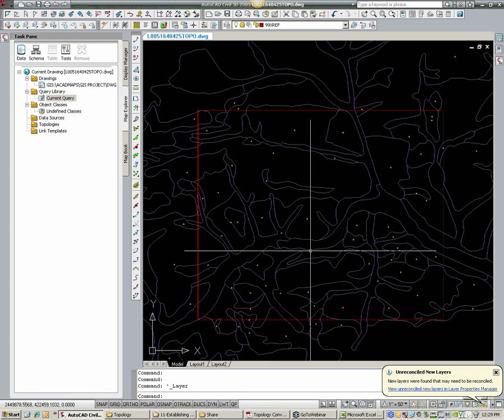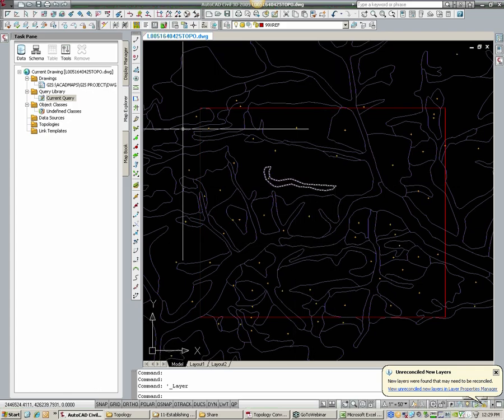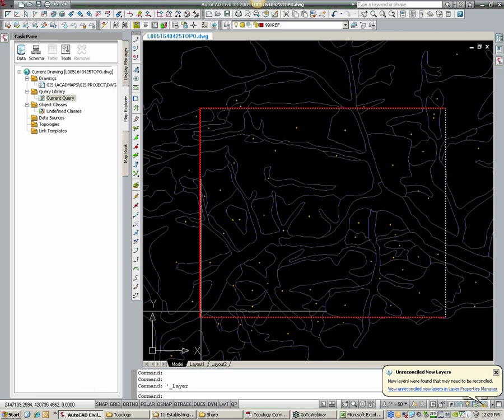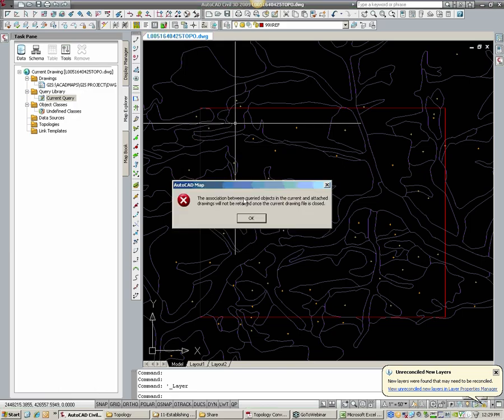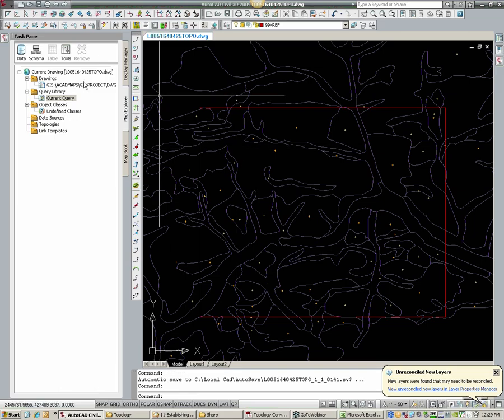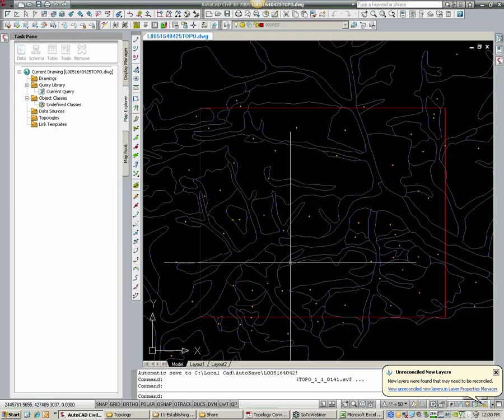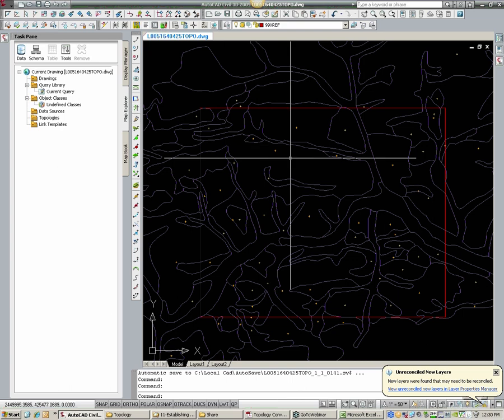Then the next thing I'm going to do is I need to bring these soils into my little area here. So what I need to do is refine these soils, and this is a very difficult part of this procedure. This is where people get bound up. That little message, I need to detach my map from the W drive. So I figured out a workflow to do this as easy as possible, and let me show you what the next step would be.